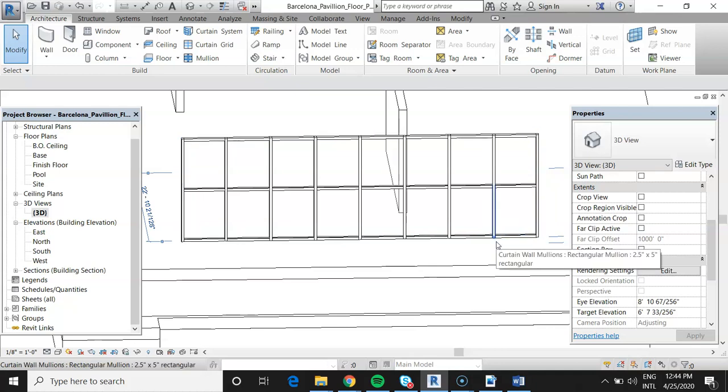So I hit the tab button. Now we have that vertical mullion. Then we jump to the horizontal. It's this whole storefront, the shape handle. That's not actually an object. So that's how we scroll through and get all the different pieces.